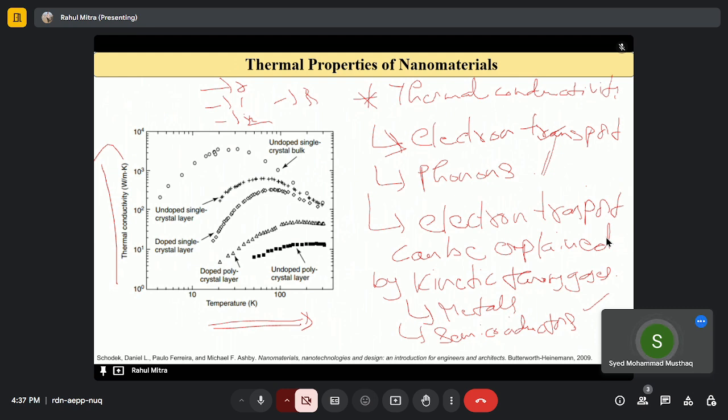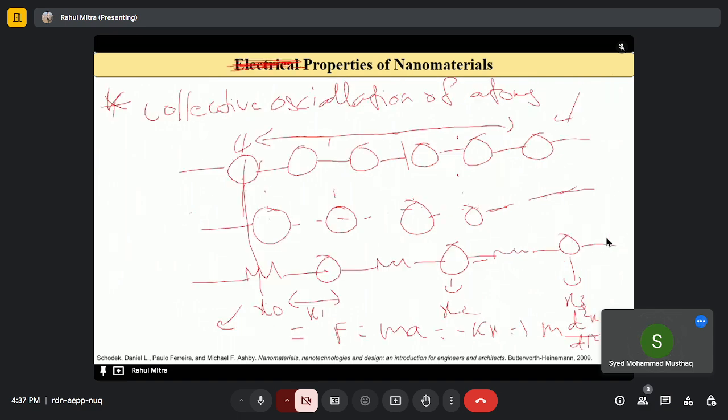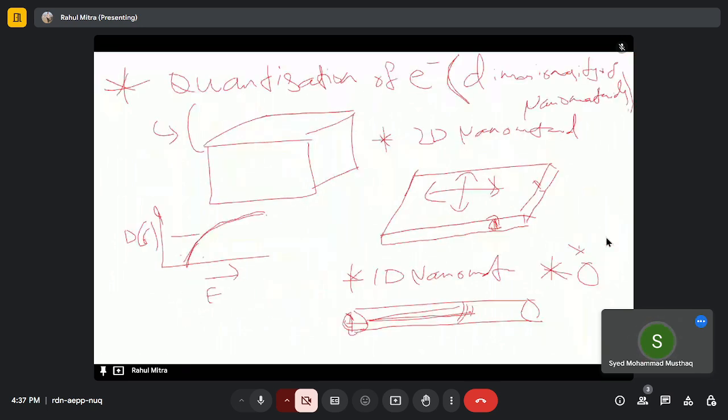So let's just do a brief recap. In the phonon conduction at the nanoscale, quantum confinement, the discretization, the quantization, and the classical scattering effects take place. In bulk homogeneous non-metals, the wavelength of phonons is much smaller than the length scale of the microstructure, but in nanomaterials, the length scale of the structure is similar to the wavelength of phonons. So the scattering intensity decreases, right?